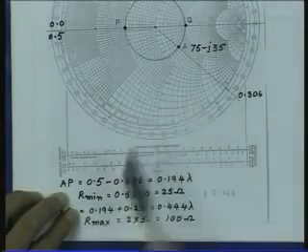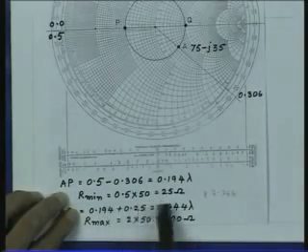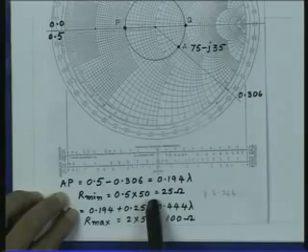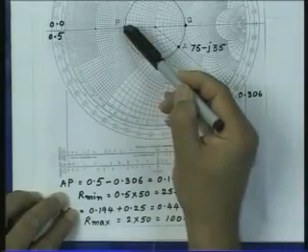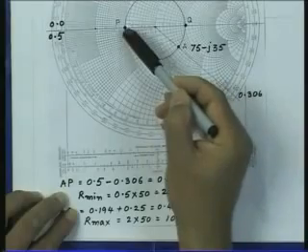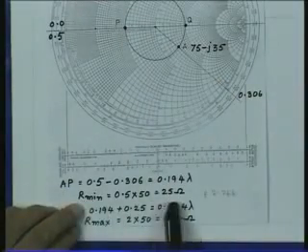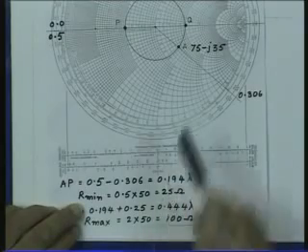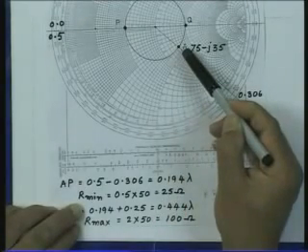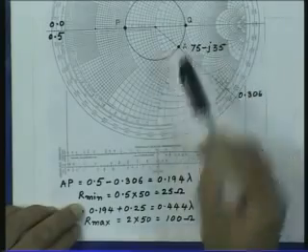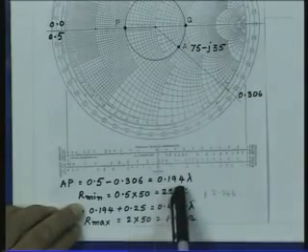and that will be the 50 ohms multiplied by the normalized value here, which is 0.5. So, now I get the impedance to be matched will be 25 ohms, if I insert a length of line between the load and the transformer of 0.194 lambda.